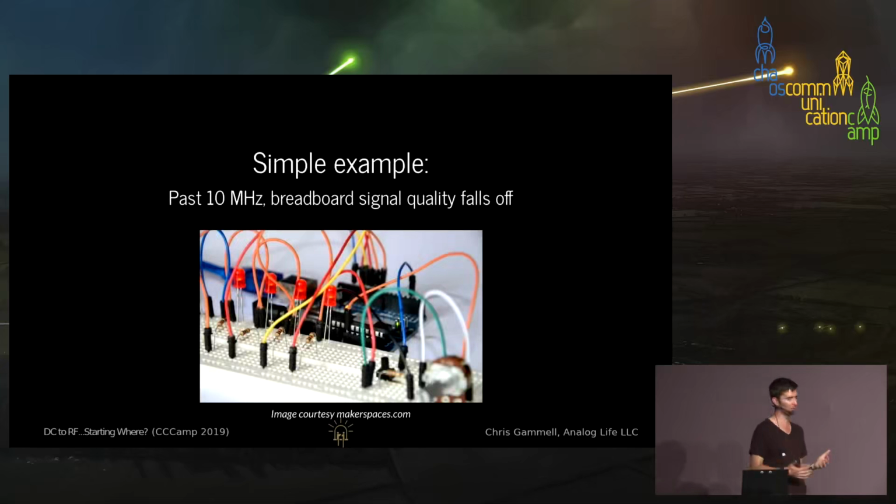As you're using a breadboard, breadboards usually operate fine, even up to 10 megahertz. If you're blinking something at 10 megahertz, you're probably not seeing it. But say you're operating a clock on an ATmega328. That works fine at 8 megahertz. But if you're trying to pump it many more megahertz than that, you're going to start to have degradation issues. And that's because of the inductance as you're starting to wire from one point to another. Basically, not just the wires that they show here, but then the strips of metal that are underneath the breadboard as well.